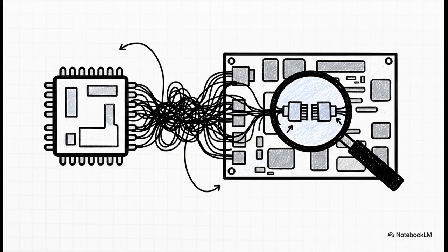However, you will eventually have to leave the sandbox. When moving from the emulator to reality, remember that while generally any x86 family CPU can control these devices, there are always hardware quirks. Differences in the base I/O port numbers between different CPU models might actually require you to use some tricky electronic equipment to alter the connections and make your tested code interface properly with the real board.